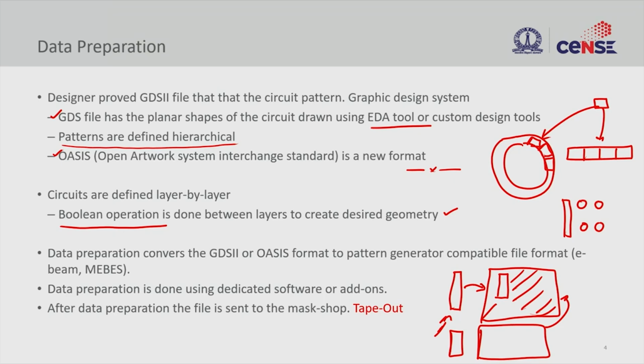and the mask preparation team also converts the data format. The GDS is the design format that you give. This is the graphic design system format, and they will convert that into a different pattern generator file format that is required to write the mask.